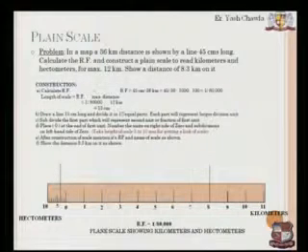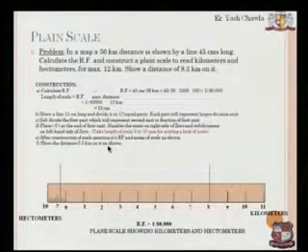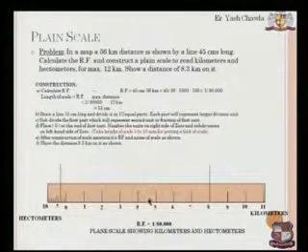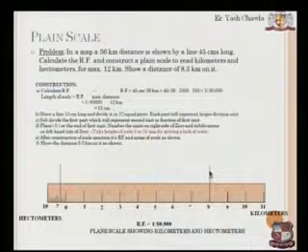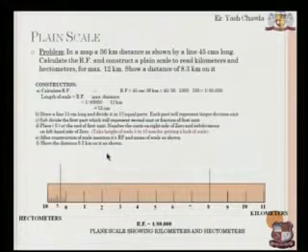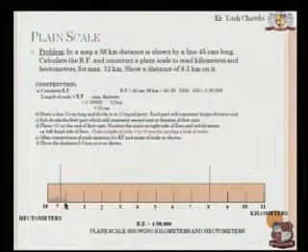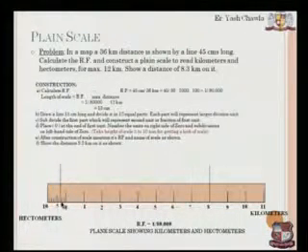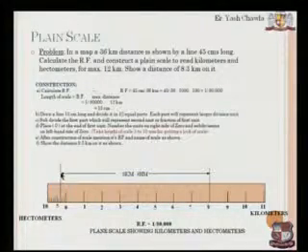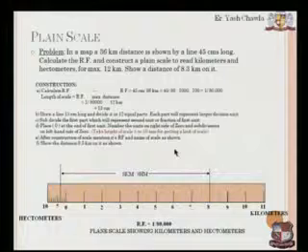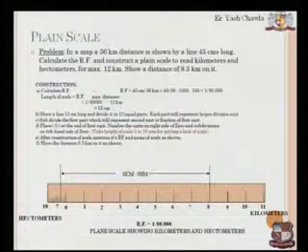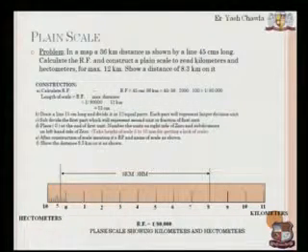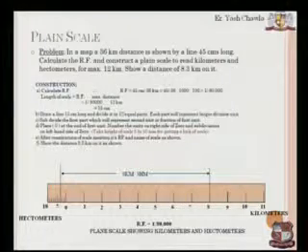The next thing is I'll take the marks. The first thing that I need to mark is 8 kilometers. So my first line would be from 0, this is 1, 2, 3, 4, 5, 6, 7, 8 kilometers. So this is 8 kilometers. Again I need 0.3 kilometers, so I'll go back. I have divided this into 10 parts, so each part is 0.1. So 0.1, 0.2, 0.3. So this is 0.3 kilometers. So this particular distance will be 8 kilometers and 3 hectometers. So we have the solution for this particular question. Any other interpretation of plane scales can be made in this kind of manner.